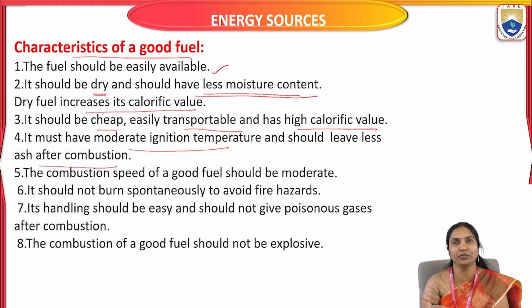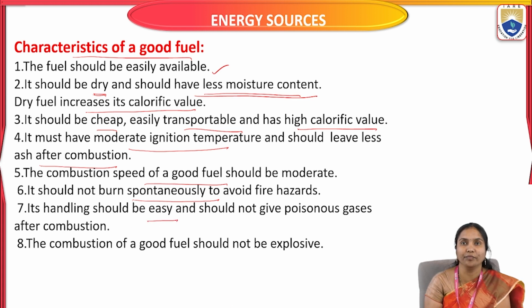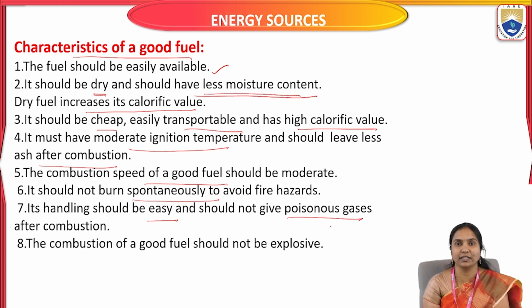A good fuel should have a moderate ignition temperature, and its combustion speed should be moderate, and it should not burn spontaneously, to avoid fire hazards. Its handling should be easy, and after combustion it should not produce any harmful or poisonous gases. And the combustion of good fuel should not be explosive. These are the main characteristics of good fuel.